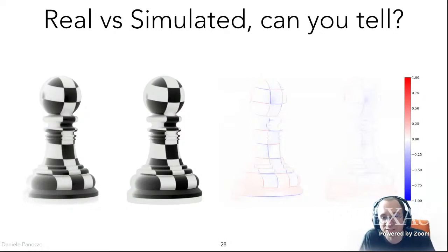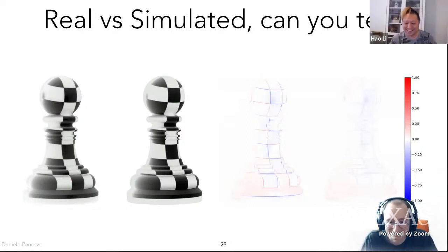So what we did here is we used a commercial camera where we can have raw readings from the CCD. And we discovered that this is super important because, for example, many cameras have corrections for broken pixels, or they do crazy averaging when there is a pixel that doesn't have the right binning. And all of these, it's easy to deal with if you have control over it. But if you have all these automatic ways of fixing the image that you get, it's going to be harder and harder to control. But we didn't try yet, so I don't know. This is my biggest fear. After this talk, they'll know how to denoise it.